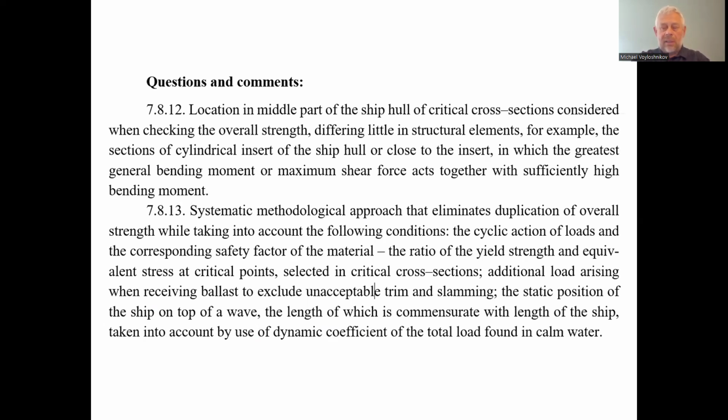On the other hand, it can be excluded by the use of ballast in the bow, in the peak bow sections of the ship hull, for example. In this case, it is not so logical to consider together the increase of the bending moment caused by the reception of the ballast and the reduction of the permissible strength caused by the possibility of fatigue failure, because the reception of the ballast reduces the possibility of fatigue failure itself.